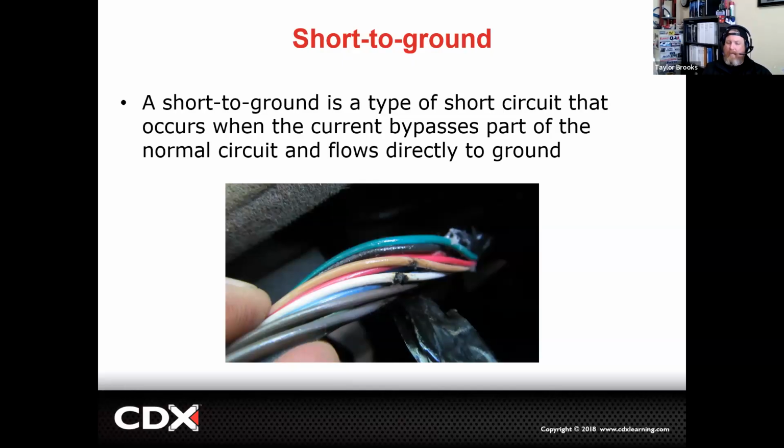The last set of codes that you can get that are kind of troublesome to diagnose are going to be performance or rationality codes. Now, those codes are looking at a set programmed algorithm the vehicle should be operating in, and the vehicle is operating just outside of that, but is functioning. So the PCM is going, hey, I don't like what's going on here. We're going to keep the vehicle running, but I'm going to set that performance or rationality code. That is where you do very much want to look at freeze frame data when you get those types of diagnostic codes.